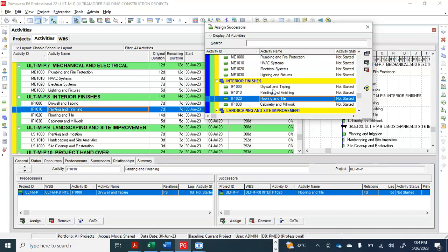Very good. There must be some days we give to flooring and tiling. Then when you have finished tiling some places, they can start painting some and then progress to the other ones. So it depends on the nature of the project, but they can't start at the same time. Ideally, if you paint the wall of the room and then come and put tiles, when you are doing the skirting of the tiles, you use raw cement, which stains part of the painting. So it's better you do your flooring and tiling, and the skirting round the walls, before you paint. Then no stains again.